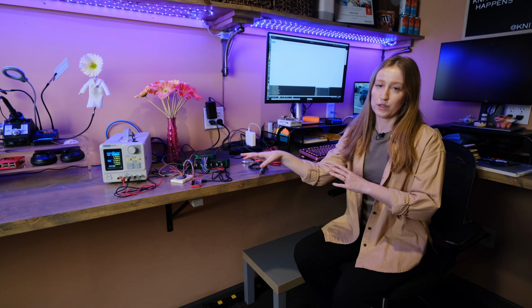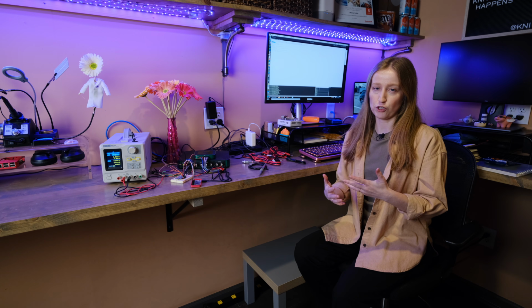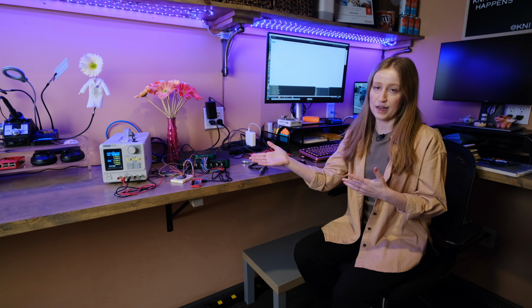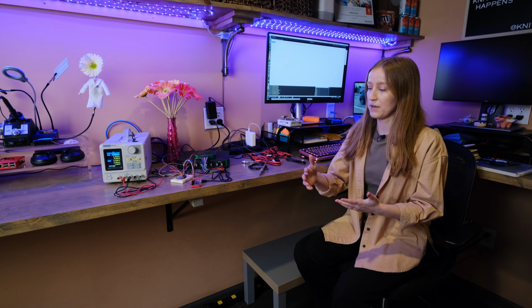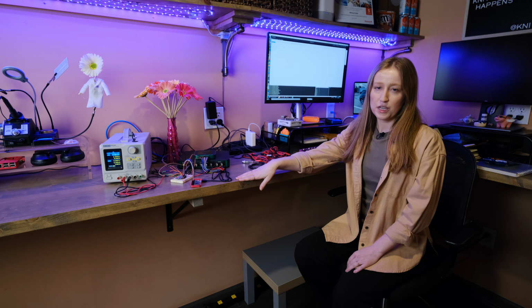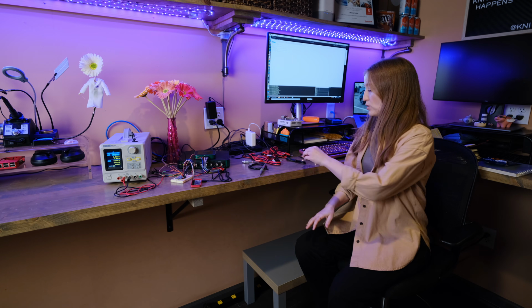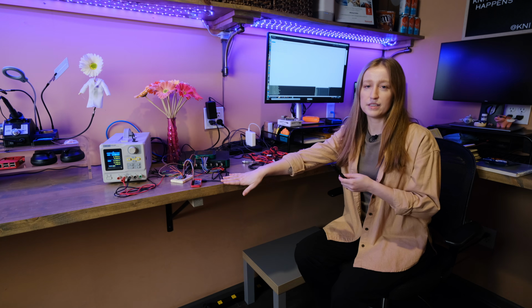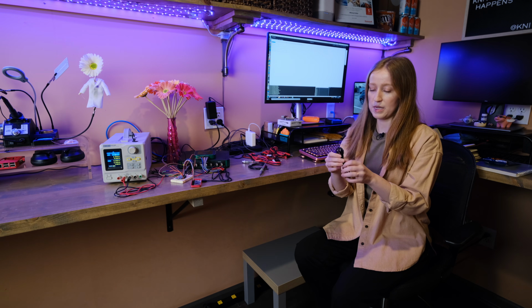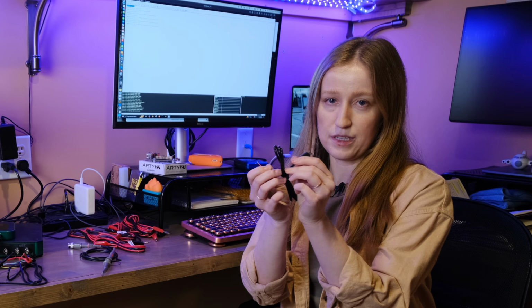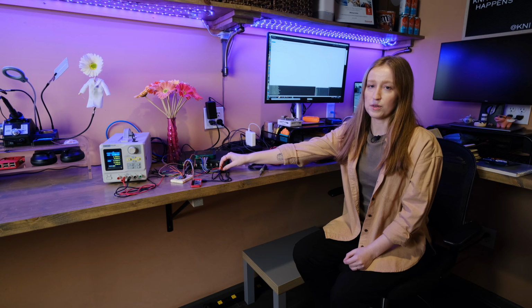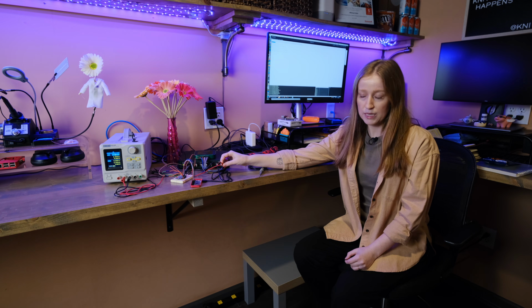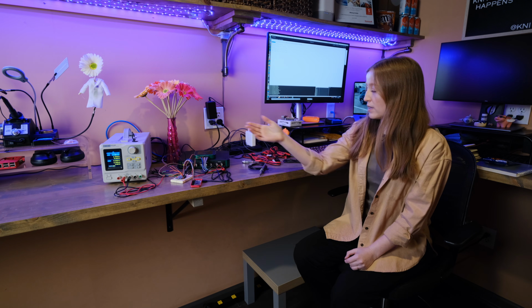So now that I've gone through my entire setup and how I've chosen the particular instruments I have, I also want to make note of how I've connected to them specifically. Pretty much any cable comes with a flying lead version, so that's what I chose for the Raspberry Pi since it's powered by micro USB. I found these micro USB to flying lead cables, which then allowed me to connect with my standard clip leads going back to my power supply.